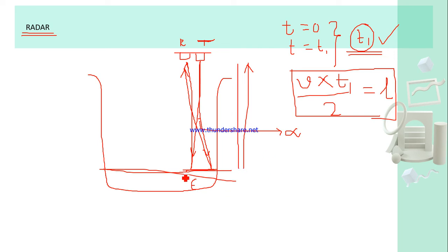Say this liquid is creating some vapor, or it is evaporated and deposited as a layer on the receiver transmitter or something like that, then this also in turn can reduce the intensity of the signal, which also can cause the error in the measurement. So for that you can use some guided tube or guided one rod, simply here you can use.